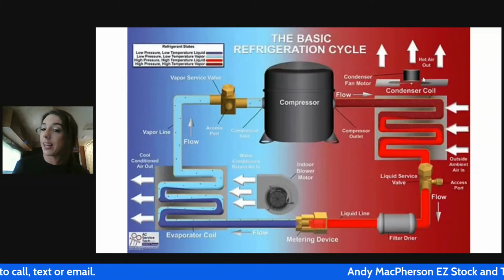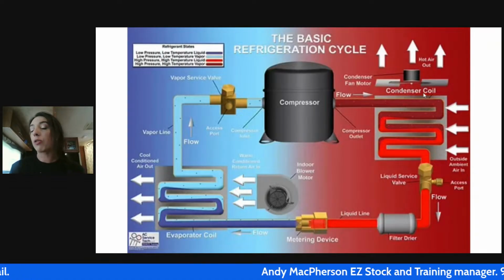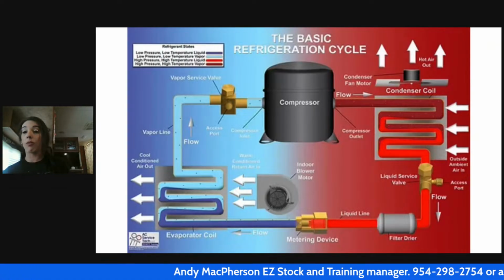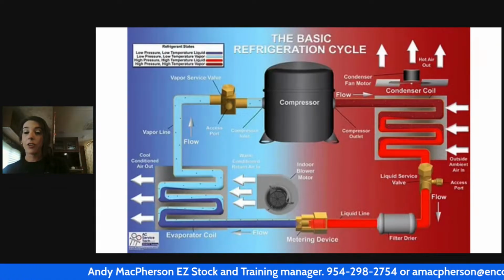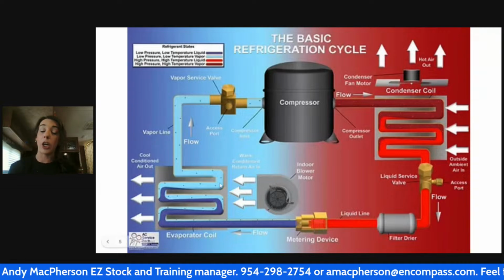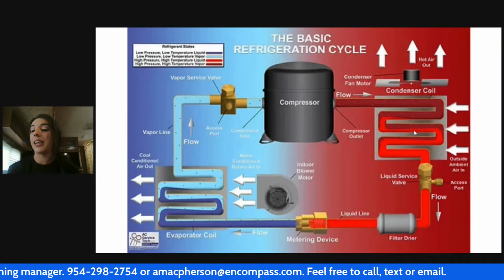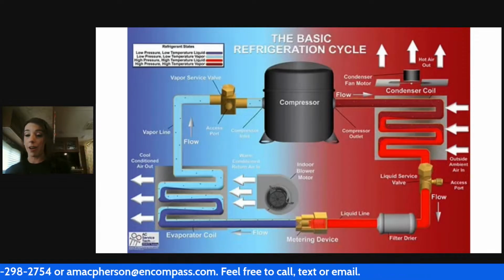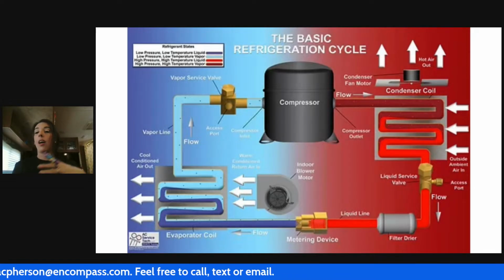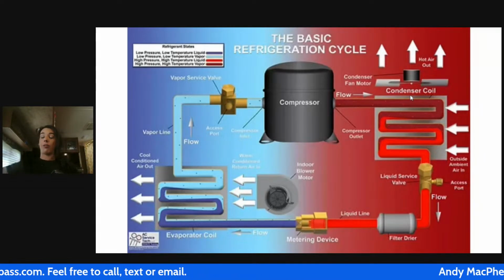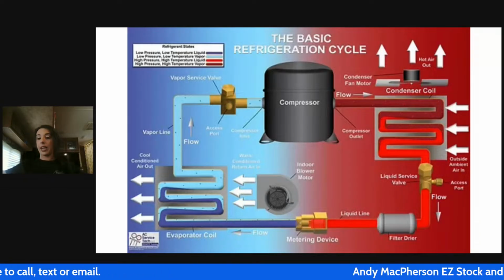Now, the fan is another story. The fan is rejecting that heat to the outside and removing it from the refrigerant. So whereas the evaporator grabs the heat from the room, the condenser does the opposite. It gets rid of the heat out of that refrigerant. So the condenser fan blows the heat, rejects it outside where it is not there to make anybody sticky or sweaty